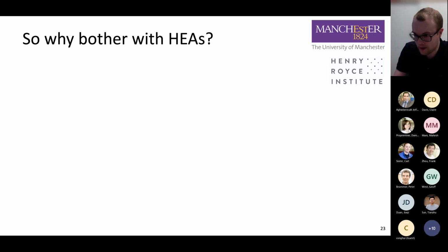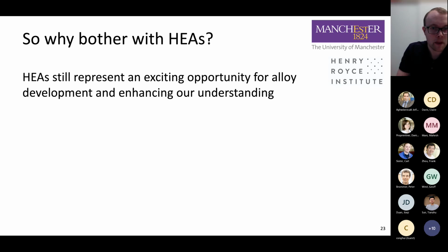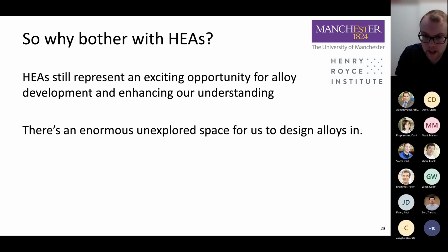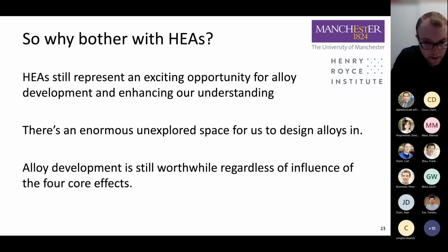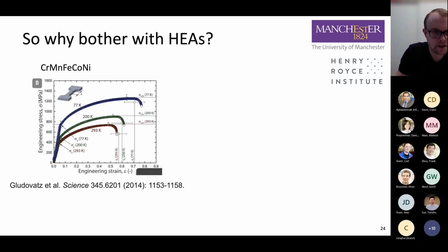So on the basis of that, as I was just alluding to, you might ask, well, why bother with high-entropy alloys at all? Well, I would argue, and lots of people in the community still argue, that they represent an exciting opportunity for alloy development and enhancing our understanding, particularly of solid solutions, concentrated solid solutions. There is enormous unexplored space for us to design alloys in, and alloy development is still worthwhile regardless of the influence of the core effects. So there are still certain applications, and we're about to talk about a set of applications, where it's still worthwhile pursuing them, despite the fact that they might not all have sluggish diffusion, for instance.